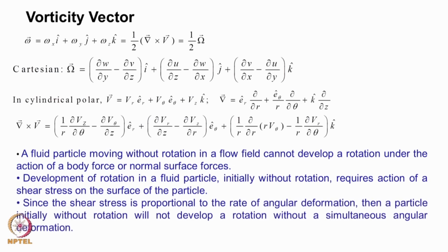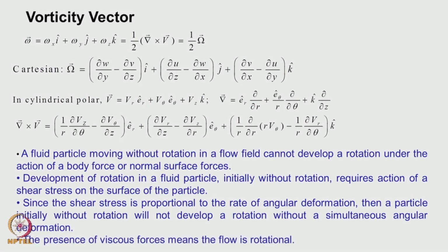Since the shear stress is proportional to the rate of angular deformation, a particle without initial rotation will not develop rotation without any simultaneous angular deformation. So, for a fluid to have rotation, viscous force, which actually results in the form of a shear stress, is responsible for rotation.